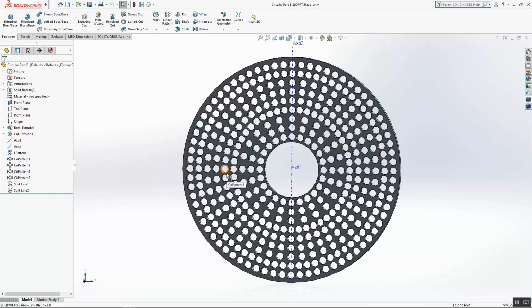That could be a lot of contact pairs depending on how much displacement we're applying, depending on how compliant our material is. And if we're trying to correctly size this to be able to withstand a certain amount of rotation or a certain amount of displacement, maybe we need to play with the number of holes, the size of the holes. It could get relatively complicated.